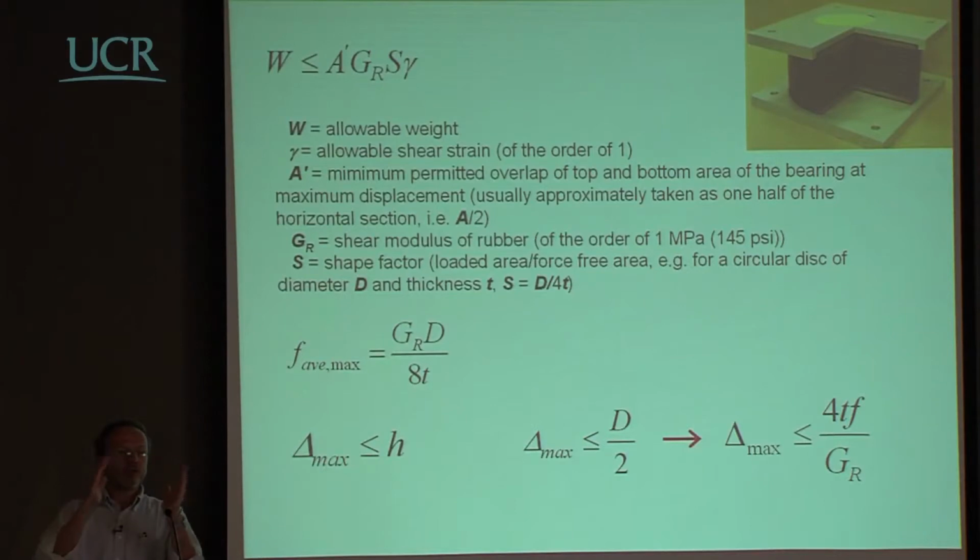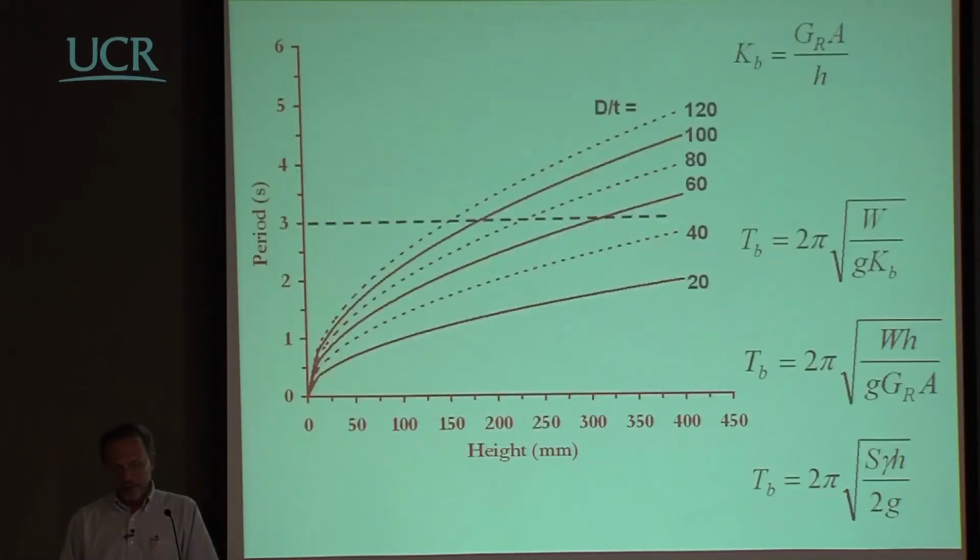Actually, the rubber could go much more than that, but this is what is normally used to design one of these devices. If you do all this calculation, you end up that a device of this sort is normally capable of sustaining a load in the order of 10 megapascal. So it's comparable with concrete or something like that.